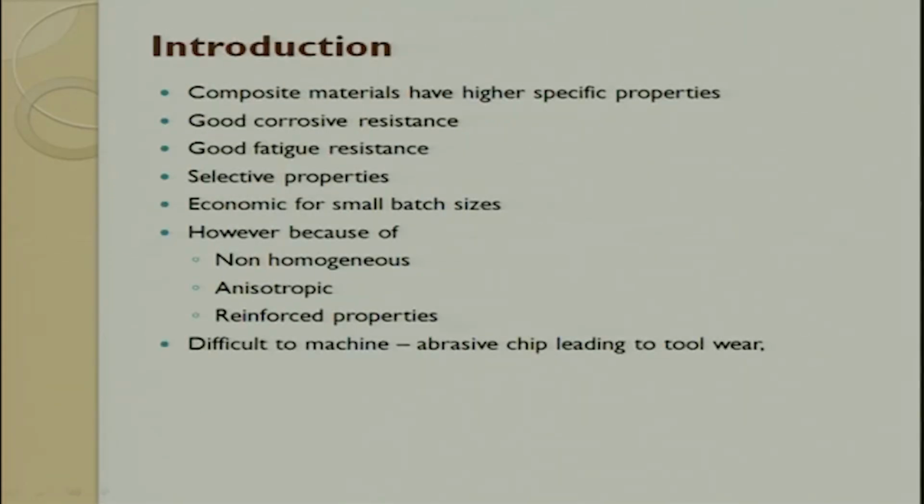When you want to classify machining processes, we classify into two things. One is called contact machining, the other is called non-contact machining. In contact machining there is always a tool which comes in contact with a workpiece. The moment there is a tool in contact with a workpiece, the tool has to be harder than the workpiece. The geometry is given to the tool, which will have a relative motion between the tool and the workpiece to create any feature of your choice. The examples of contact machining are drilling, milling, turning, boring, grinding. These are some of the examples.